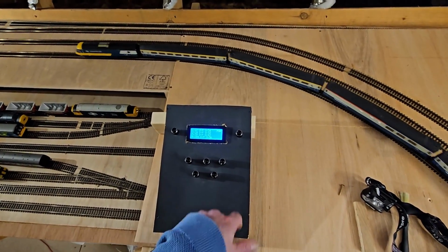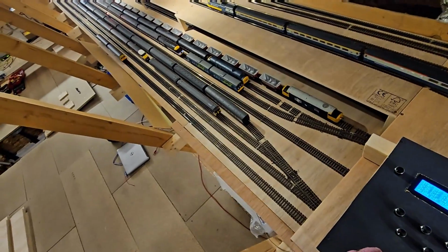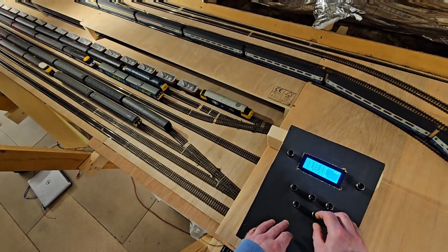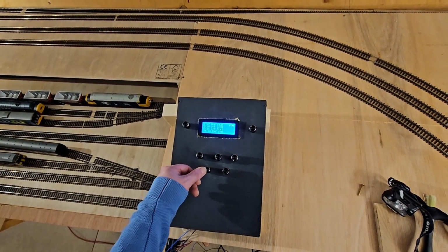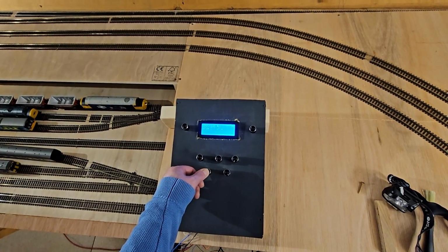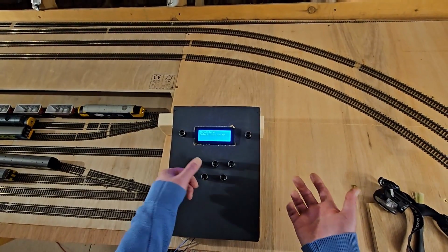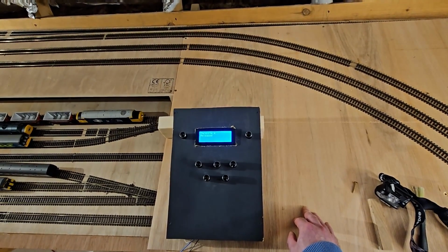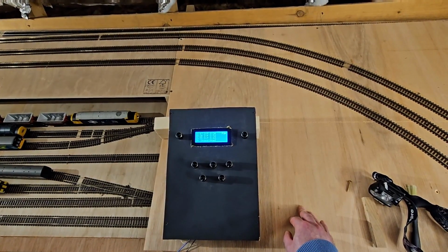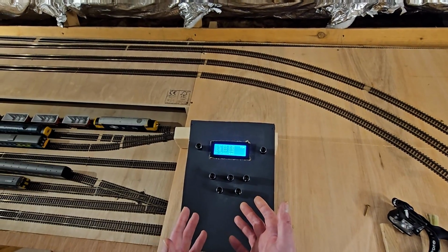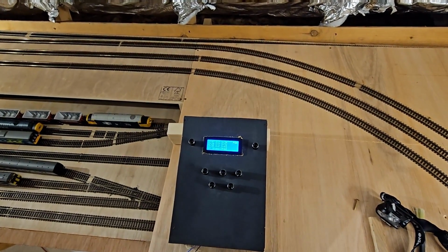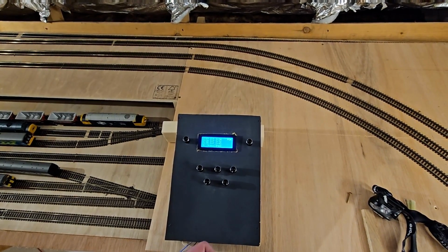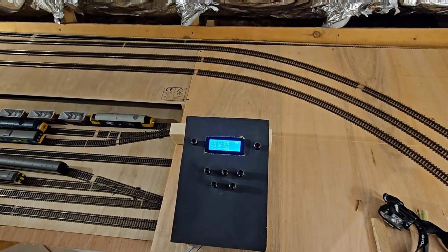I can always, if I get one parked, that 101's just kind of safe. If I let that, was that on number? See, that's on number 4. So let that get down to the bottom. One button press will stop the train and set it to speed 0, and then I can either go back in and pick another train to drive, or if I let go, it'll release it and note it down as unassigned in the list, so I can come back. It's a good idea to unassign them, I think, because if not, I do get the knobs mixed up. I'll end up driving something that's parked and into a short or a derailment, so it's useful to release them once I've finished driving them.